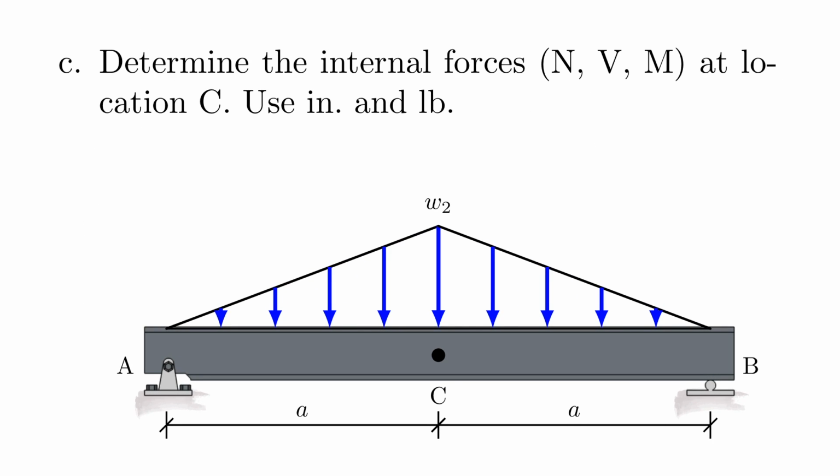Now it becomes a little bit more interesting. We have actually triangular loads, but again, you also have calculated support reactions for cantilevers on triangular loaded systems. So here you look at something very similar, except now you find the internal forces at location C once again. And once again, you just release the system, either the right side or the left side. In this case, it really doesn't matter because it's truly symmetric. So it's really up to you. And you find N, V, and M as for all of these problems. So there's no real secret here that I can share with you.